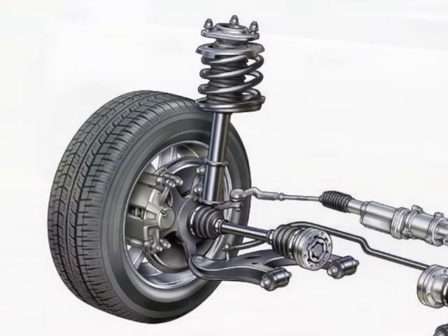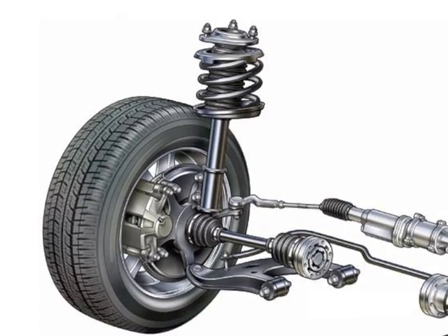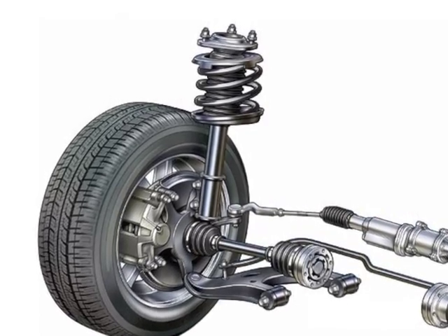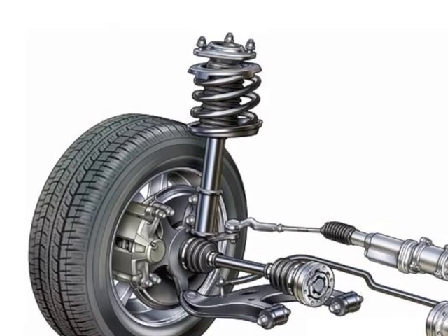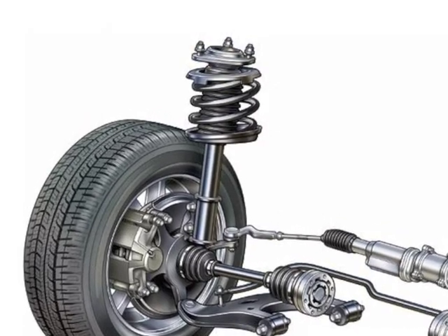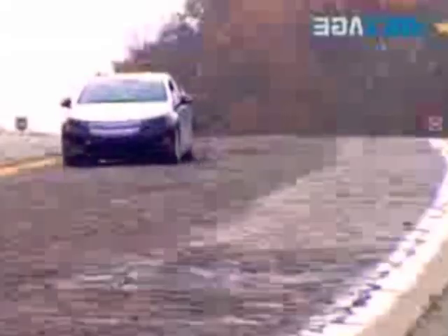The second purpose of the suspension is to protect the occupants from vibration caused by an uneven road surface. For this purpose, we need to have the unevenness of the road not transmitted through to the passenger cabin. Therefore, a suspension should act like a filter. It should pass some frequencies and reject others.